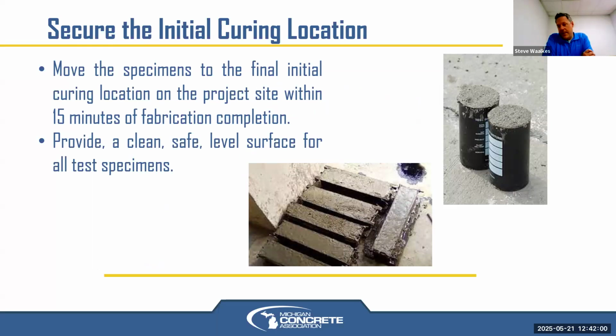They are allowed to be brought back to the lab only 8 hours after they've had final set, which usually happens within the first 8 hours of a typical concrete mix. So usually the next day they can be brought back to the lab as long as the lab's within 4 hours of the project site, because 4 hours is the max transportation time. And then they are not allowed to be left in the field longer than 48 hours.